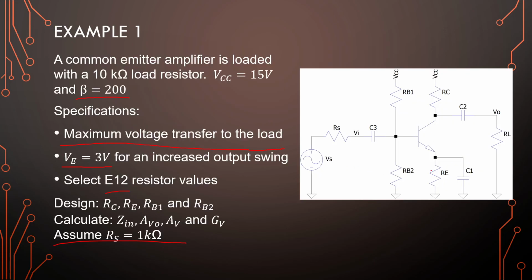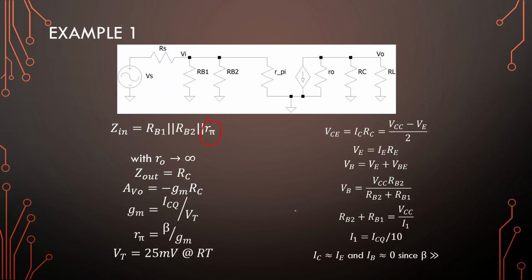And then if you selected your collector current first, your VE value might also decrease if you're designing for VCE equal to IC RC. So a different approach is to start from a specific input impedance here and then design from back to the front. Okay, so you can approach this from a different end. And that will become apparent with our choice of RS later on.